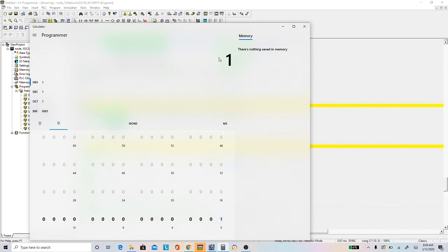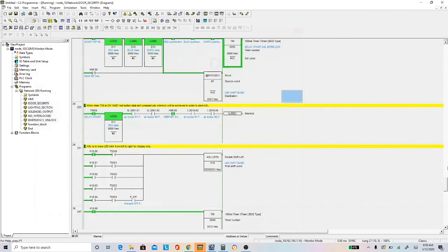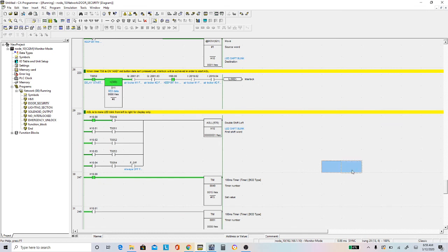So this one will be a 1. You want to turn on all these 4, it will be an F. If you want to turn on just those 2 or 3 will be D0, and this is hexadecimal format. So that's how you pretty much control bits inside a word. So you can see the same format and see how all this lines up like this, and the bits inside H10 is what's gonna keep it shifting.